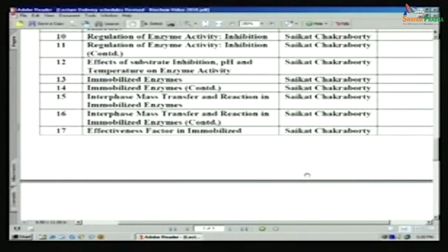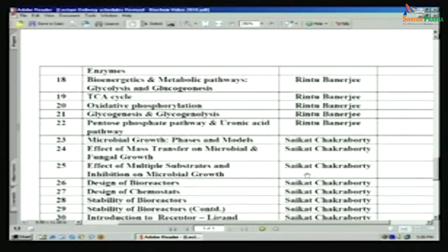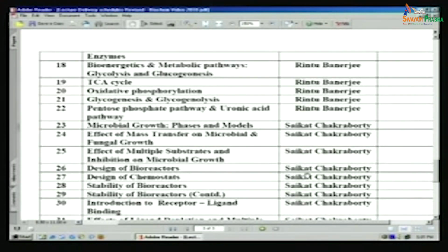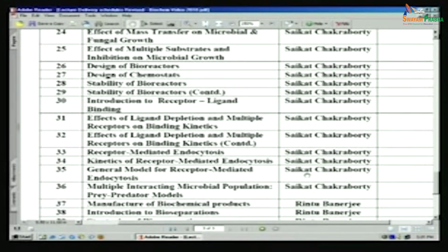Now, once we have looked at cell growth, after these cells grow, or while these cells are growing, in both cases you can engage them in biochemical reactions in reactors. These reactors are called chemostats. Chemostats are nothing but CSTRs, continuous stirred tank reactors. But in the biological, biochemical parlance, they are called chemostats. And so we'll try and understand the dynamics of it, the design of it, and some of the pretty interesting things we will do, which you probably have not done in other courses, is the stability analysis of bioreactors. Okay, and substrate inhibition and multiple steady states and so on.